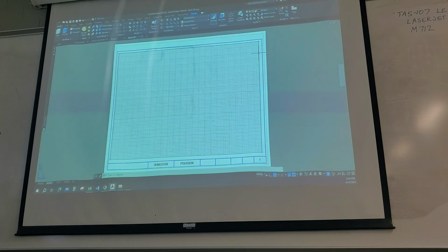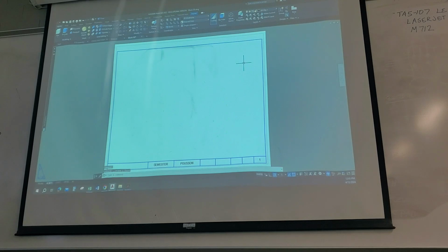When you're doing a 3D object, the next step that I'm going to do is I'm going to erase that viewport. If you're doing section views of the object, which we'll talk about probably in a couple of weeks, that would be a little bit different. We would still want our viewport for that. But for what we're doing right now, just bringing that 3D object in for a front, top, right side, ISO type, orthographic and isometric views, we erase that viewport.